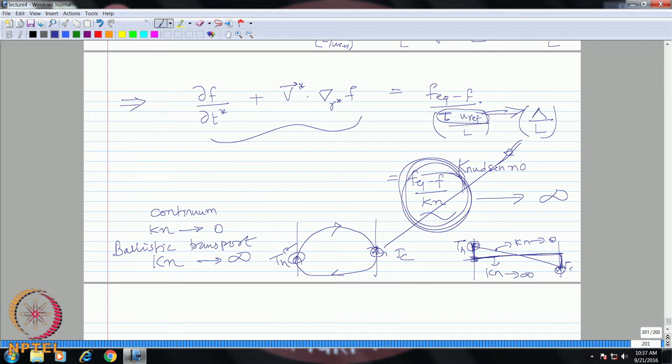So, now you understand that the Boltzmann transport equation is a self sufficient equation, it carries all the information regarding what kind of regime you are working at. So, you do not have to worry whether you have to solve a separate equation at Knudsen number going to 0, because the same Boltzmann transport equation will be equivalent to the continuum equations at that limit, whereas it will also behave like a proper nanoscale transport equation at larger Knudsen numbers.